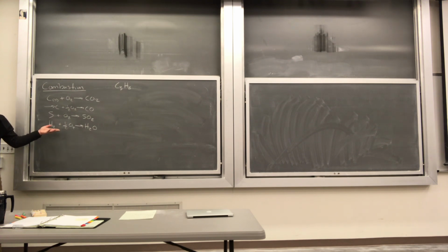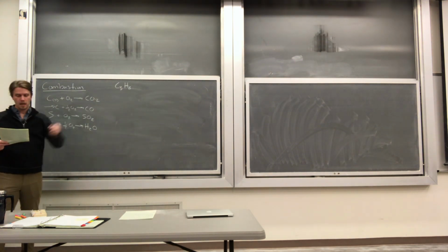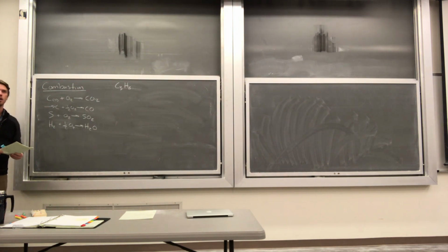Right? So in combustion, we're not going to necessarily be burning a fuel where we exactly know what the composition is. So when we're burning a fuel, you'll get a weight percent of the fuel for every element. You can convert that to a mole percent. Then you take a basis of, let's say, 100 moles of my fuel. You'll know exactly how many moles of carbon atoms you have, exactly how many moles of hydrogen atoms you have, and you know that for every 2 hydrogen atoms, you use 1/2 of an oxygen molecule. Does that kind of make sense?